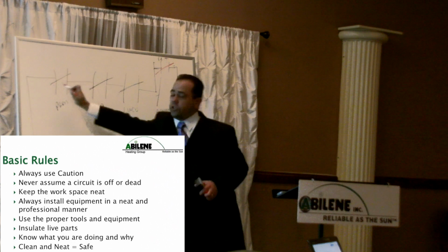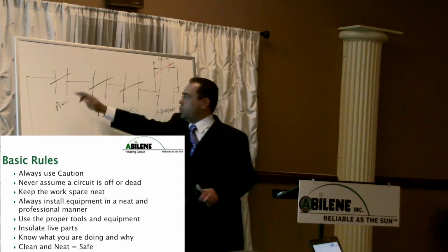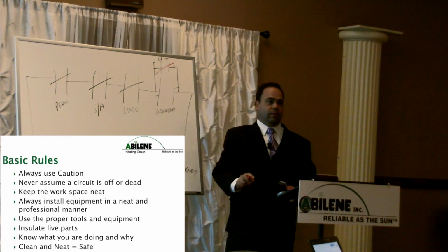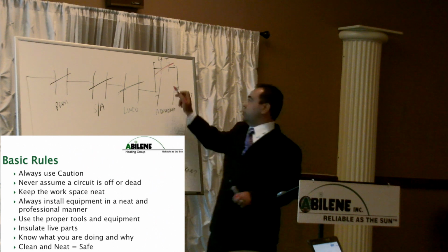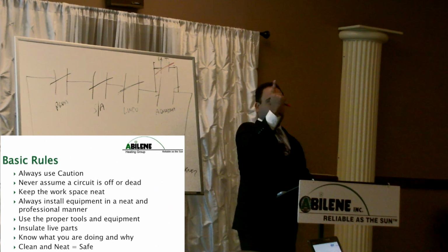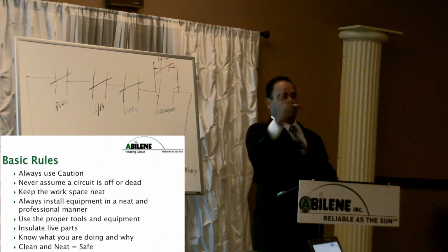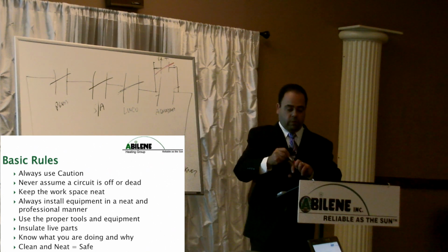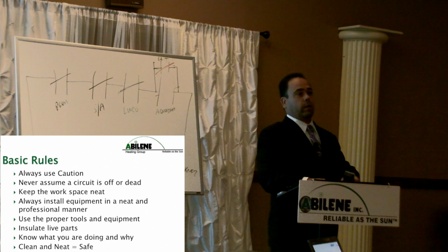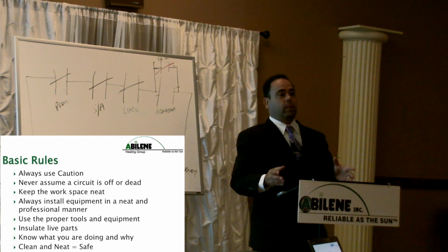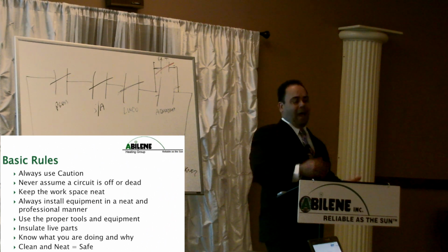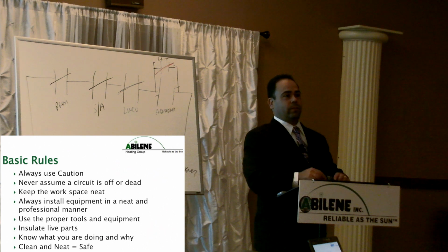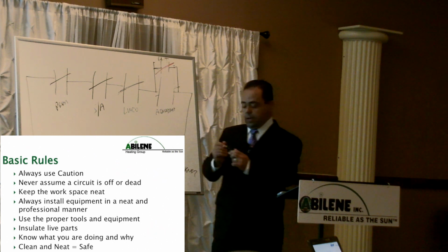In a series circuit, all switches have to be made. In a parallel circuit, only one has to be made, because it's in parallel, right? Very important when you're doing burner wiring. All the limits, or the high limits, have to be in series. If you're wiring them in parallel,